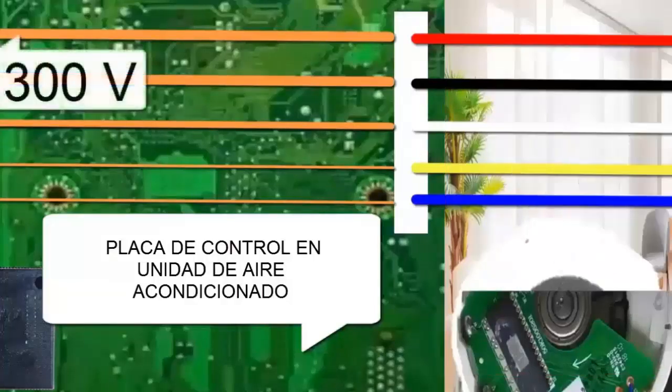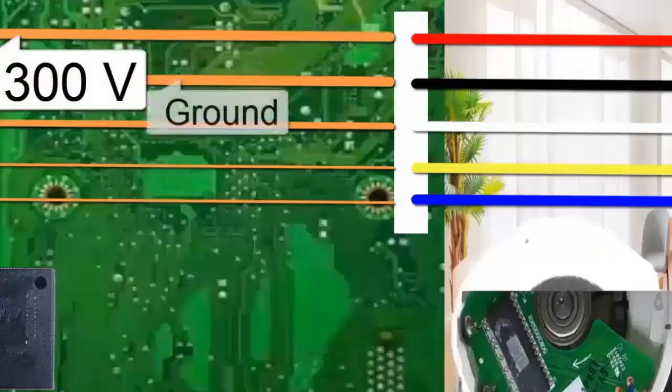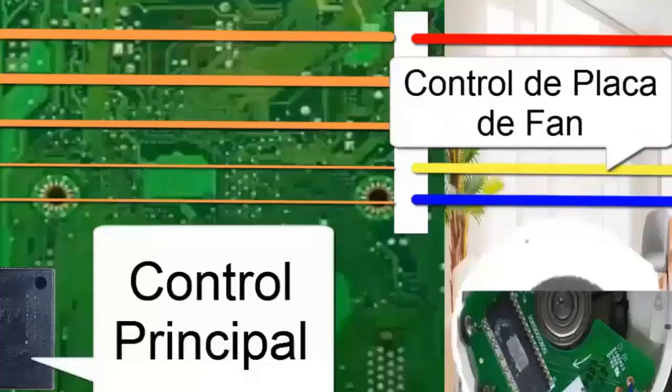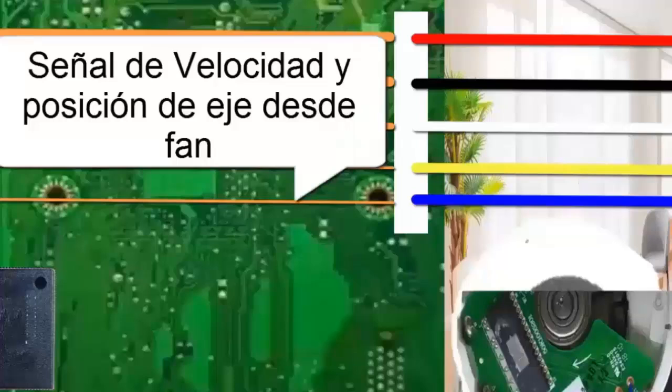C. These 5 cables are generally color-coded as follows. Red, high voltage DC power supply, approximately 300 V when the network supply is 220 V. Black, ground or common for the entire electronic board. White, power supply to the internal electronic controller of the BLDC fan, usually powered by 15 V. Yellow, signal or pulses from the main board controller to the internal BLDC motor board. Blue, signal from the BLDC motor to the main board indicating the speed and position of the BLDC motor rotor.